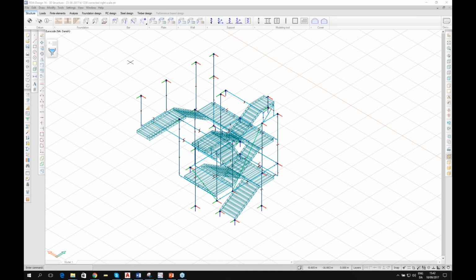When you do a point-point connection, you need to consider the peaks. So normally what I do is I pick the dimension of the plate on the bolt, because I found that reasonable. But this is something you need to consider, and then you can get out all your forces, export it to Excel, and test it in your bolt software.